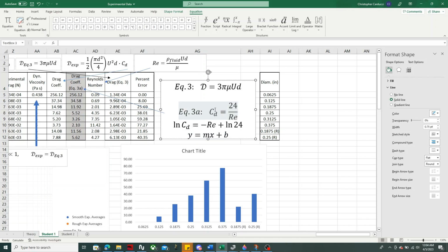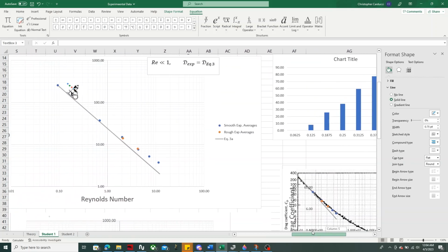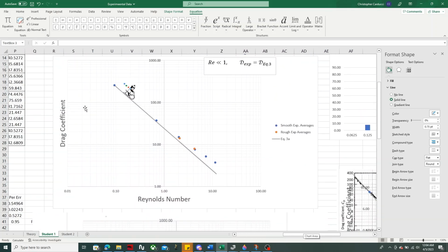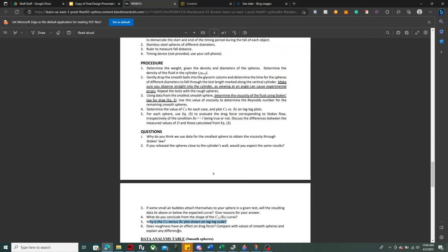If you're really interested, I can explain this more in person to you. But just so you know, with the log-log plots, you could see that spread of data. You wouldn't be able to see anything interesting. It's all going to bunch up when the Reynolds number is less than 1, and then when Reynolds number is greater than 1, we have Reynolds numbers that can go to a few billion. It's going to be really hard to see any kind of meaningful change in your drag coefficients. And this is all about visualizing your data.